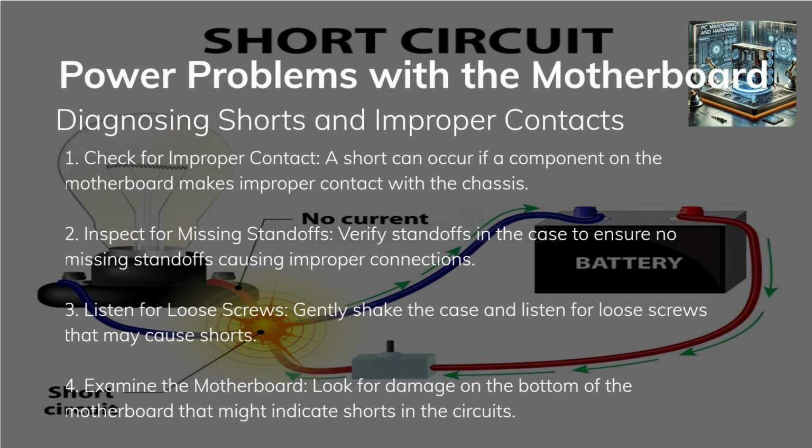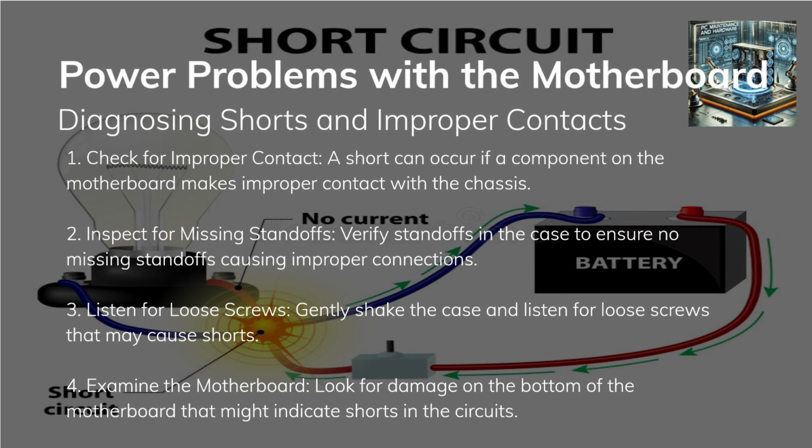A short in the system can happen when a component on the motherboard makes improper contact with the computer's chassis. One common cause is a missing standoff, which is supposed to keep the motherboard raised and properly isolated from the case.